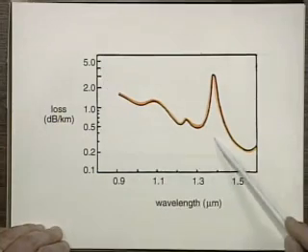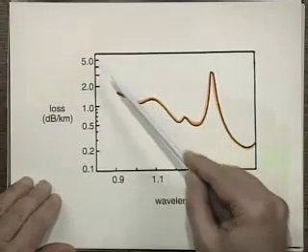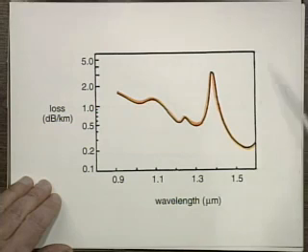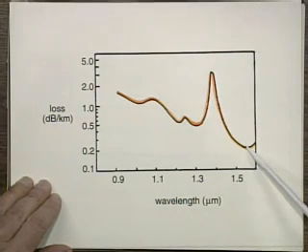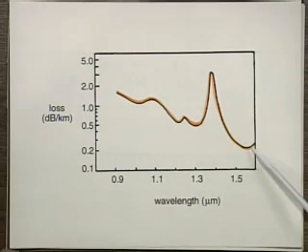That's on one side. So as the wavelength gets shorter, the scattering gets larger and larger, and then you're in trouble. That's the same reason why the sky is blue and so on. Now on the other side, not shown, is essentially the material absorption, the infrared absorption and so on for the quartz, for the glass.